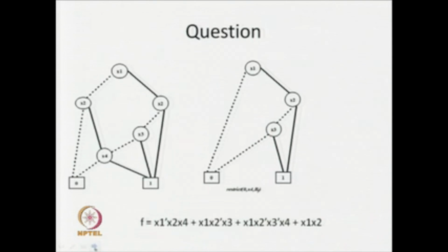Now, first we are saying that apply the restrict operation over here, restrict 0 x4 on f. So, what is the rule? Since we are going to restrict this function on a variable x4, we are going to look for all x4 nodes and we are going to remove this particular x4 node from this BDD. When we remove this x4 node, then its outgoing edges will also be removed. So, these two will be removed.